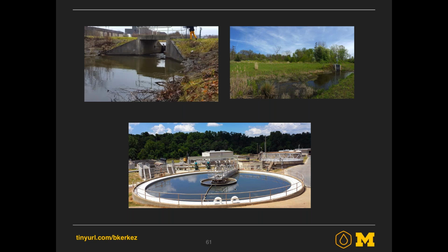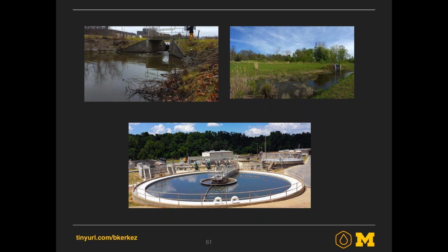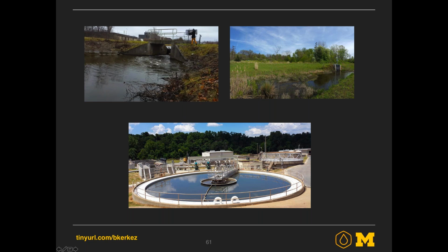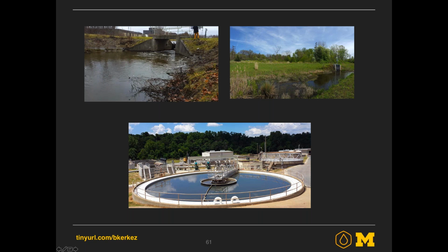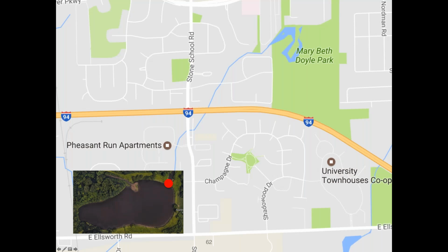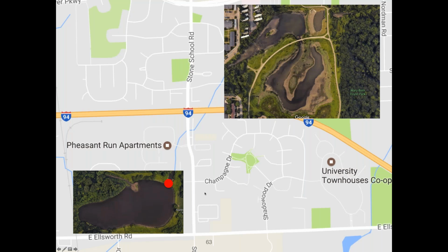To promote that kind of idea, we started saying there are obviously all these local benefits that can be achieved. What can be done at the watershed scale? Because now if you control it at very fine granularity, you could be messing up the watershed even further at a system scale. So can we control individual sites to benefit the system? What we started doing was looking at the site that we're controlling. This is the valve that we located. We hold back water here based on whatever decisions we make to open and close the valve.